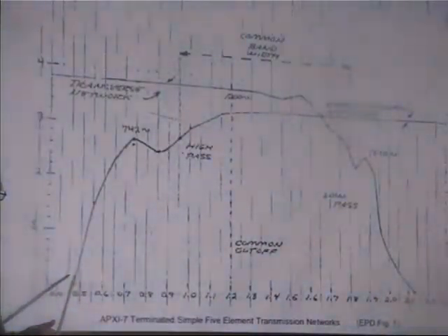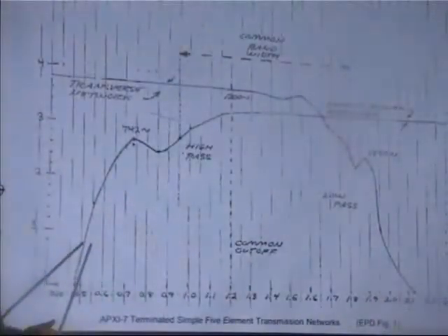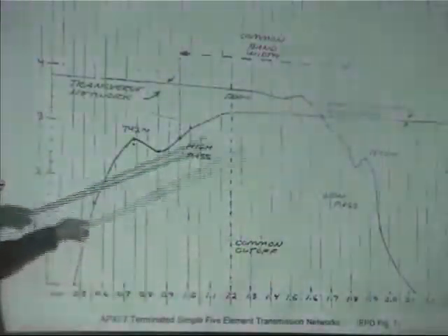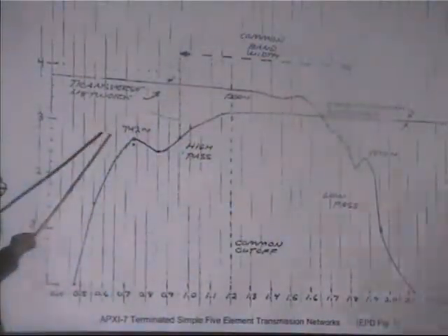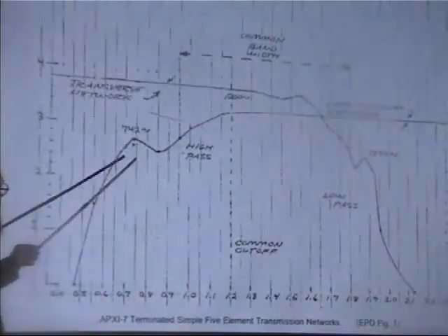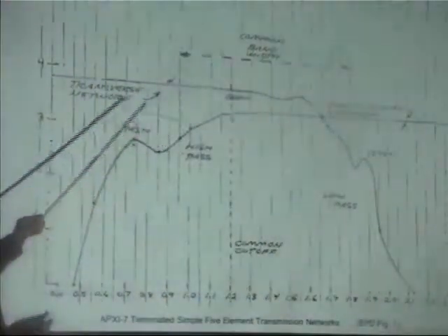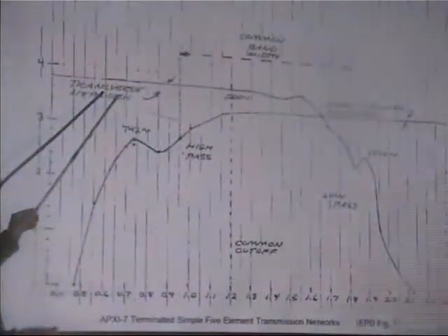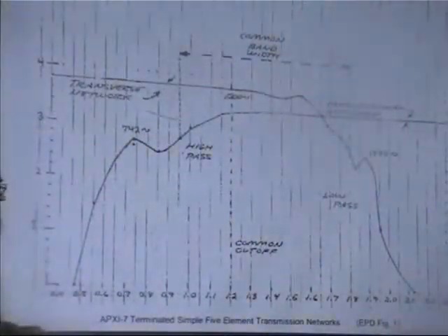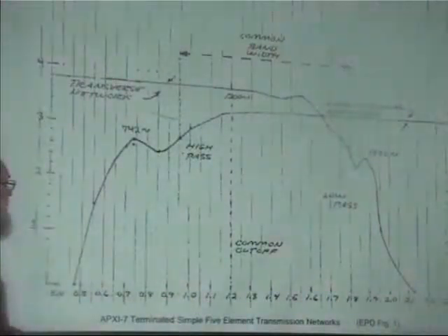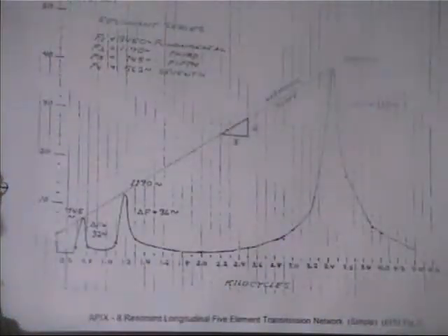If the frequency is low, it cuts off. But as the frequency raises, then it comes up to the ability where it can operate. So we have two complementary types of waves. We have one which we call high pass, in other words, the highs are passed and the lows are cut. And we have one that's low pass, where the lows go through and the highs are cut. This is standard electronics technician terminology. Okay, let's go to the next one.